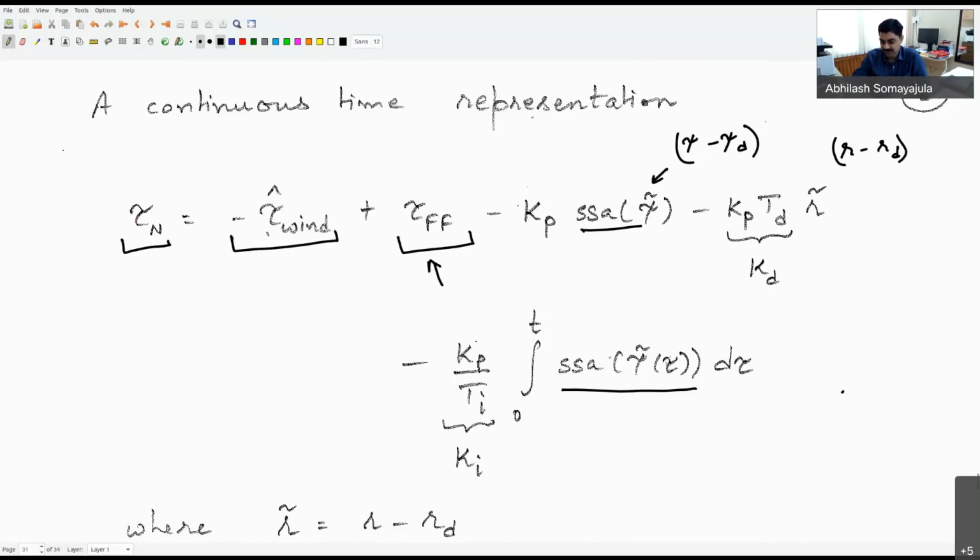So we have looked at this autopilot system in terms of a guidance algorithm, which is coming from a low pass filter giving me the desired states. And then I have a controller part, which is taking a PID control strategy in order to compensate for the differences in heading error. We looked also at the idea that the controller can include this so-called feed forward term of the wind, where we are trying to compensate for the wind gusts which might be coming into the picture.